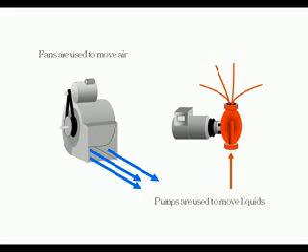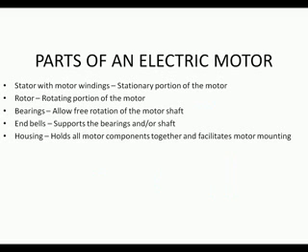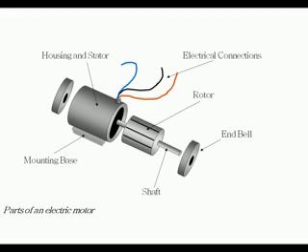First of all, in the HVAC industry, we use electrical motors to turn the fans, pumps, and compressors. We use them to facilitate the circulation of air, water, and refrigerant as well as other fluids. Motors are designed for particular applications. The correct motor must always be used, or you're going to burn out either whatever it's driving or the motor. Most motors operate on similar principles. So we use the motor on the top of the fan to move air. We use the motor in pumps to move liquids.